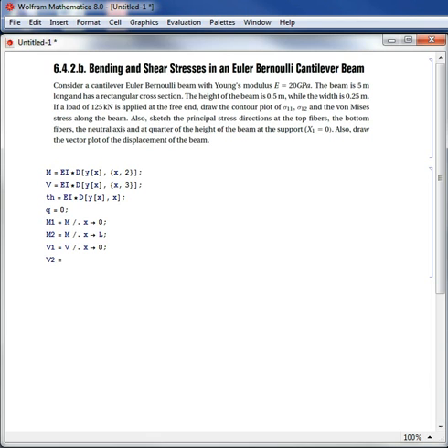The shear at the end, the second end, is equal to the shear when x is equal to L. The rotation at the left end is equal to the rotation when x is equal to 0, and the rotation on the right is equal to the rotation when x is equal to L. And finally, the deformation or the deflection y on the left is equal to y of x when x is equal to 0, and y2 is equal to the deflection on the right when x is equal to L. Now I can solve my differential equation.